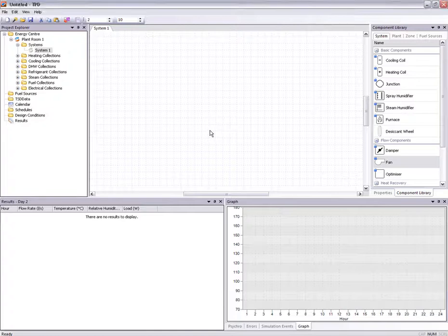In this video, I'll demonstrate Tas Systems, our component-based plant modelling toolkit. Once I've already simulated a building and found the heating and cooling loads for the different zones across my model, I can use Tas Systems to model the HVAC circuits and the plant circuits, such as the heating and cooling boilers and chillers, to determine the overall energy consumption and cost and unmet hours of my model.